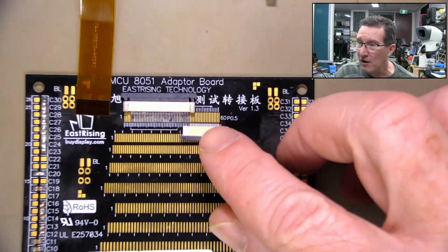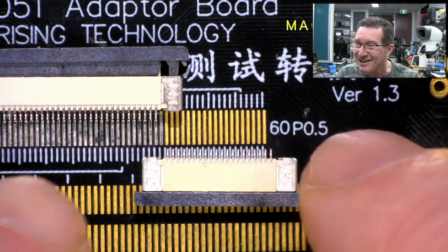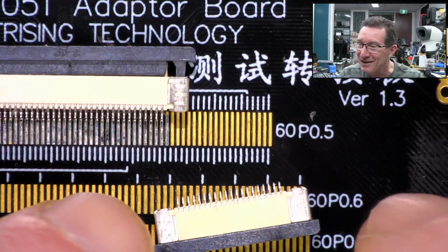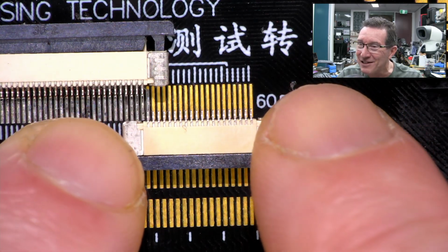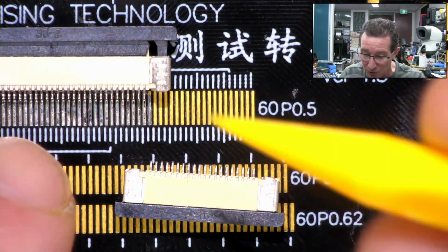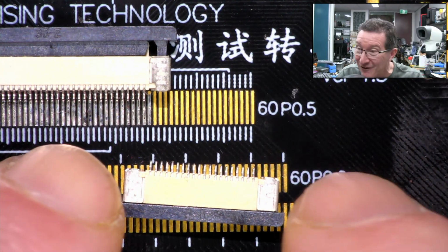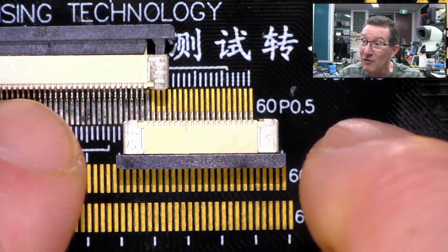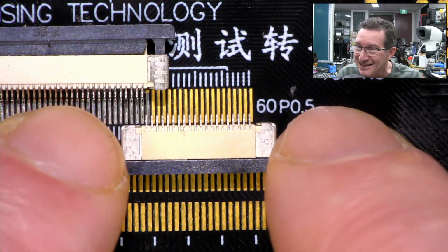Now, this is 0.5 pin pitch, and sometimes you win, because look at this. I can't fit it this way, but I can fit it in this direction, like this, and it perfectly fits with one pin. This last pin, which looks like it's soldered in, is not. It's got some solder on it, but there's no actual pin there. So I can put it in this direction, and beautiful. Yeah, so pin 1 will be over here, so I've got to flip the numbers and everything, but everything's routed out. So yes, that's a win.